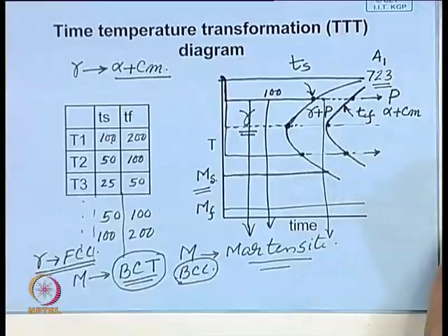So, if you retain carbon, we know that the diameter of carbon atom is a little more than the interstitial site present, and we also have seen in the last class that the interstitial site, particularly in BCC, that octahedral site, is not symmetric. In two directions the gaps are different. So, if you want to keep this carbon atom in the lattice site and still retain the structure as BCC, what happens is that in one direction the lattice increases. That is the C axis.